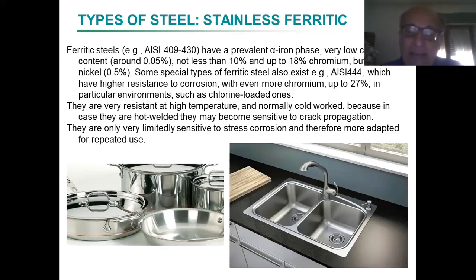In general terms, they are less tough than austenitic steel, which is the other category, because the structure, the lattice, is less concentrated, is less packed, and in general they are less resistant to wear and to crack propagation. Although they can go up to high temperature.